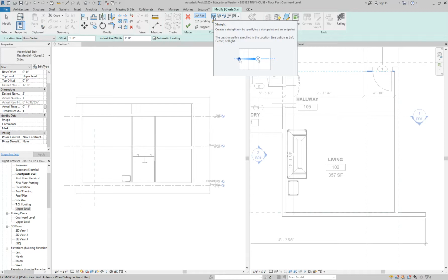I think this is the hardest disconnect for people, because they assume that when they're drawing the stairs they also need to draw in the landing. So it doesn't feel intuitive to people to draw stairs, stop drawing stairs, and then come back and start drawing stairs again. The other tricky thing about this is, let's say our stairs are 3 feet wide. Depending on where you click, do you see how you can kind of have an awkward run-in?